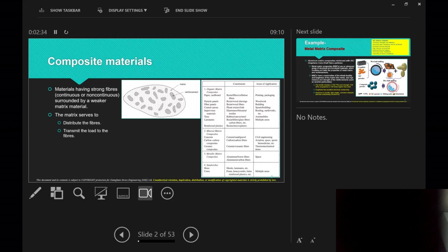Like the layers of metal slipping, falling apart, because there's no things in the material to block the movement of the layers. Well, you're saying it's got a different failure mechanism, but it's not really. In fact, metals have got superior failure mechanism compared to composites, as we will see in the subsequent lectures. That's one of the advantages of the metallic materials, in fact. Pressure, altitude, it's like loading. And what happens? You load it a couple thousand times and it fatigues the metals. Yeah, it's got enhanced fatigue performance. Yeah, it's a lot better in terms of fatigue.